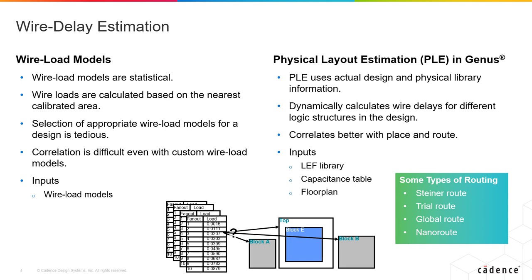Furthermore, we use a guess for the fan-outs and loads to estimate the maximum wire length, then calculate the corresponding resistance and capacitance of the estimated wire length, and finally the delay of the wire. This multi-step process can be very tedious and result in a very pessimistic view of the wire delays and thus the design we want to create. Thus, wire load models can be challenging when it comes to correlation to the actual place and route tools.